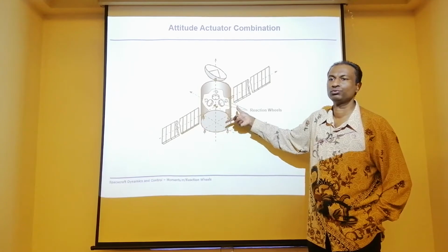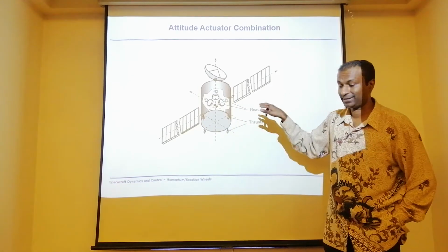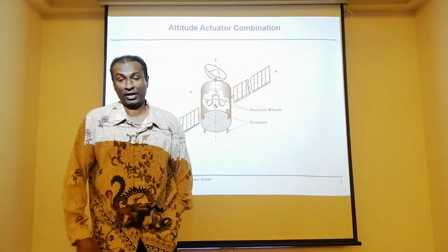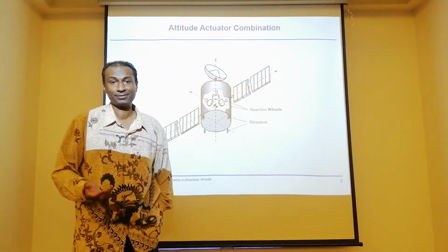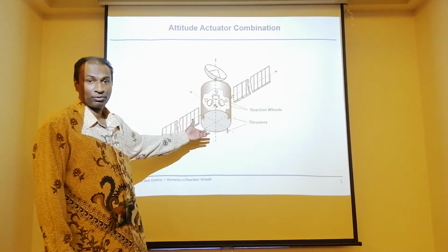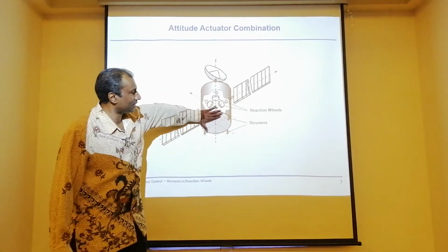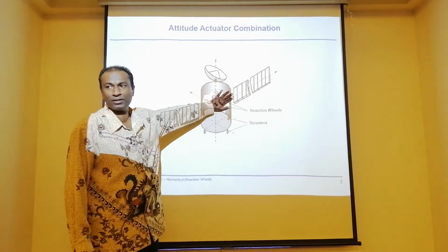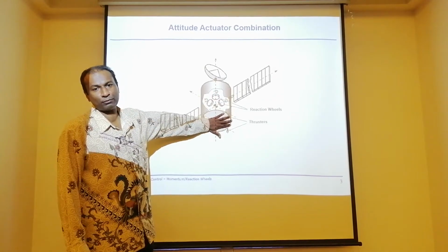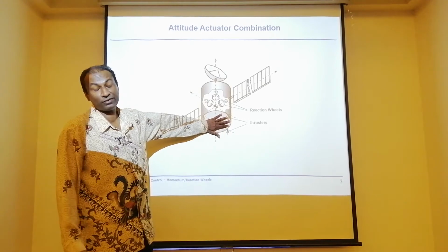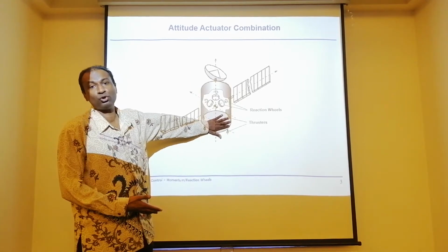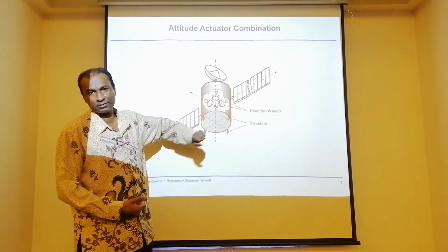It should be doing both, which means that the life of the satellite can be long, can be 5 years, can be 10 years, can be even 20 years when you have this system. But assume you don't have thrusters, you only have a reaction wheel, you'll be lucky if the satellite lasts for about 3 years or even 4 years if it is a low Earth orbit satellite. Okay?